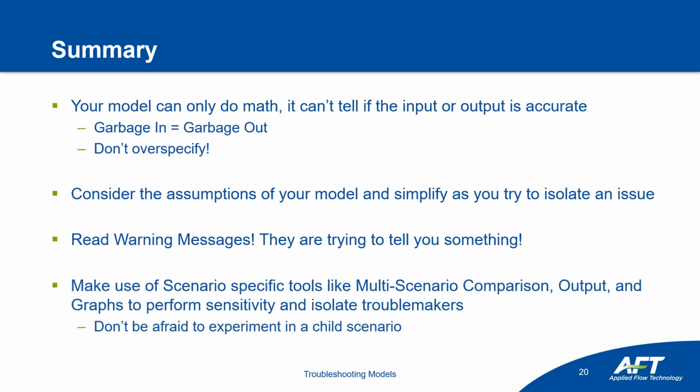Finally, make good use of scenario-specific tools like your multi-scenario comparison, trying to isolate what variable in input that you're modifying, multi-scenario output to see the consequences of those changes, and then graphs, just another way to look at that data. And what that lets you do is perform sensitivity, and you can isolate what is making all the trouble in your model. Don't be afraid to open up a child scenario, make all the changes you want. Again, it shouldn't impact your parent scenario, and it gives you the flexibility to experiment.